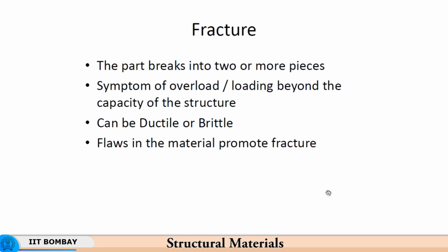So for critical applications like the rope of the lift, supposing you have used the lift for say 10 years, 15 years, 20 years, there will be a schedule for replacing the rope after a certain number of years have passed. After certain hours of use over 10-20 years, it is possible that the rope will develop a flaw. Not that the rope will fail overnight, but the flaw itself will endanger the lives of passengers in the lift.